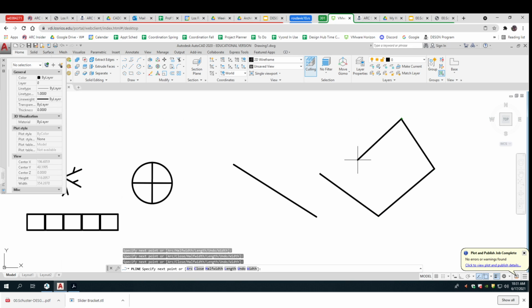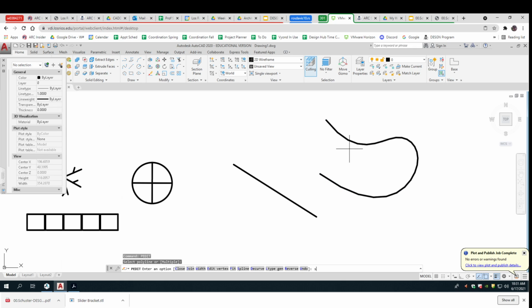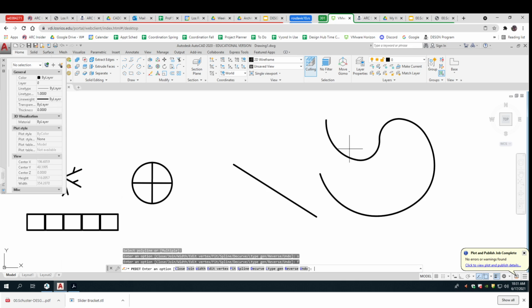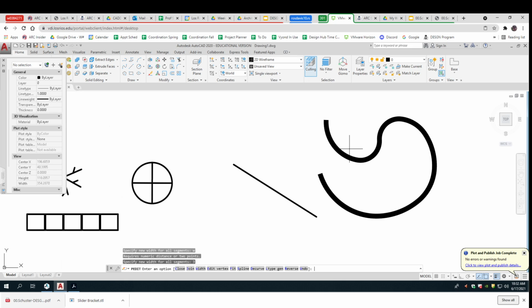now I've got a polyline. And there are some really cool things you can do with polylines because you can edit them. There are a special set of tools. So now look, I can do a spline or a fit. I can set the width. So basically the line is drawing a line segment, and the other one we're drawing the shape. I mean, essentially, when you click on it, you're selecting the entire thing you drew. Yep.